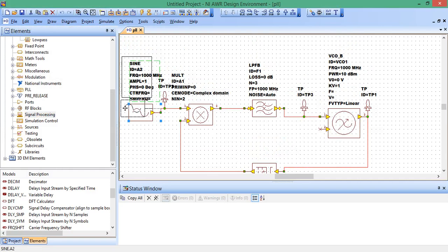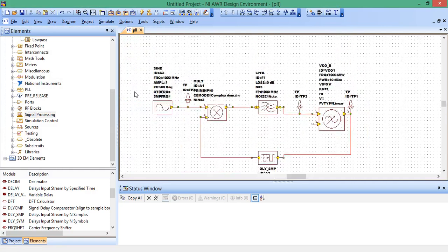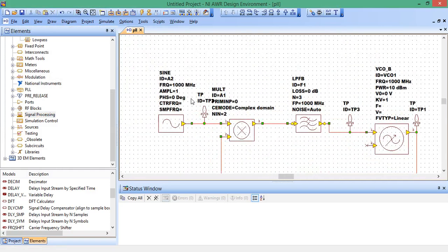Okay, now we have a bunch of parameters that we need to set here. So let's look at the input signal. The frequency we want to be 1 megahertz. Let's make this a variable, Fn. The phase, we'll make this phase in. Here's equation. Let's set Fn to be 1 e to the 6, 1 megahertz. Equation again. Phase in equals 0 radians.